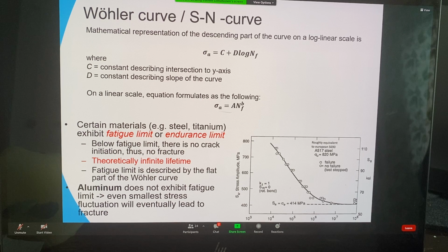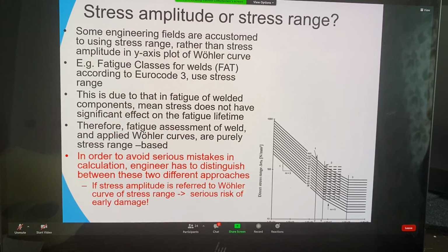The reason is probably that carbon fiber, considering the strength and the stiffness, is much lighter. I don't think the main reason is the fatigue property of aluminum, because there are also fatigue properties for carbon fibers, and for those it's even more difficult to describe and assess. So carbon fiber or generally composite fatigue is much more complex than for homogeneous materials. But nevertheless, it's true that carbon fibers are probably coming to passenger aircraft as well. They've been used in military vehicles for quite some time. Okay.